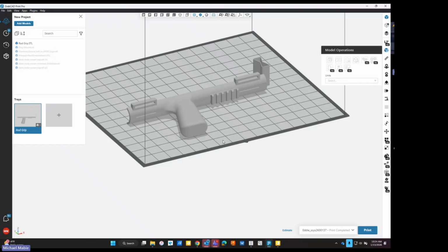As far as storage goes, nylon material is hygroscopic, meaning it wants to absorb moisture. So as much as that helps my finished part retain its flexibility and its capability, if I'm pulling out the material, I want to make sure I keep that dry. So on the Fortis stuff, that's fairly easy. We have a metal canister that has desiccant packs in it. Make sure that all the rubber seals are closed up and shut, the little door, and make sure that there's no filament extending out from the little snout or the cap.